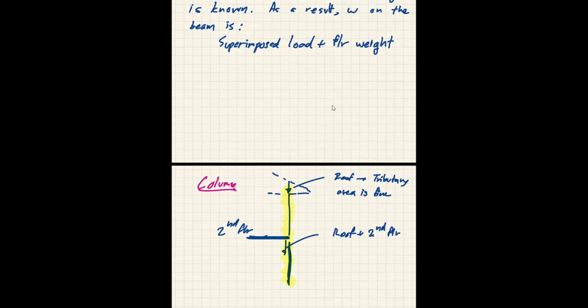So anyway, since we are not going to have that very complicated problem, and it's only 2 stories, we are not going to change the size of the column, because in typical design, the column size is changed every 2 floors. And we only have 2 floors, so it's going to be crazy to change the size of the column. So we are going to design this.